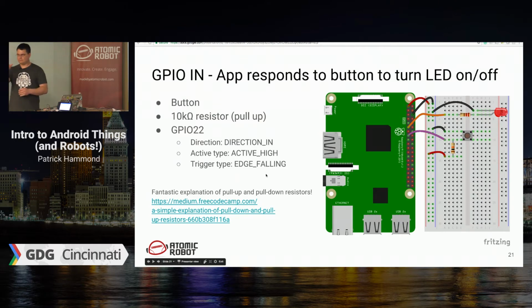So this is all kind of making, yeah, Stephanus? What do you do to take care of the contact bounce? I know that's a little advanced topic, but is there anything in the libraries that takes care of that? What do you experience when it registers twice? You would normally put in something to debounce those, so that if it sees 2 or 3 signals all within 50 milliseconds of each other, it only takes the last one or the first one or something. I got lazy, I didn't put that in there. It seemed to work well enough for my purposes, but yeah, you'd normally have something in there about that.